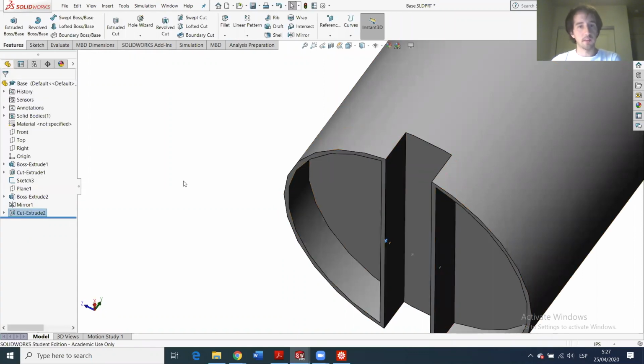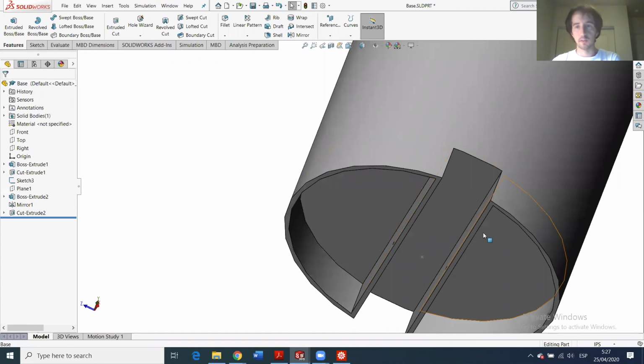Why is it better to use surface and not distances to make holes? Because if for any reason we get some error in our calculations of the distances and we need to modify this particular distance from this wall to this other wall, then if you have defined this hole up to the next surface, the depth of the hole will be updated with the distance.